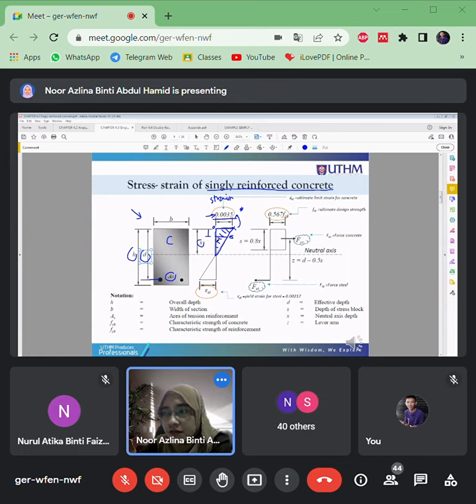Okay, so kalau more detailed analysis, you can come up with, symbol ni salah. This is the symbol for stress. Well, this is the symbol for strain. Okay, so you can know what the strain is here at this point. Okay, this one is linear. Okay, it starts from 0 at the neutral axis and goes up to the maximum of 0.0035 strain for the concrete.